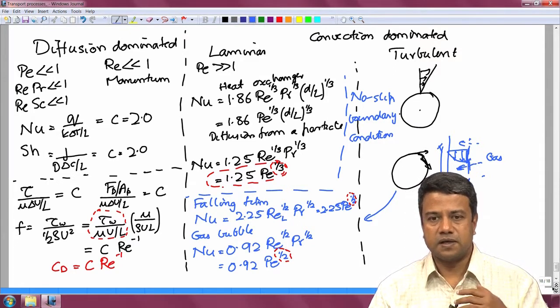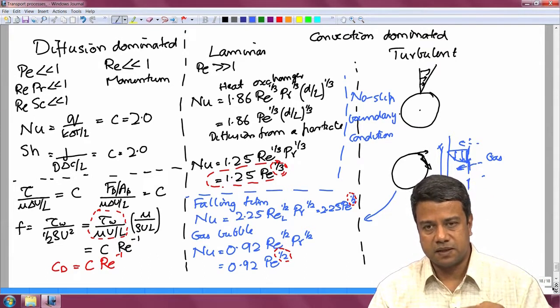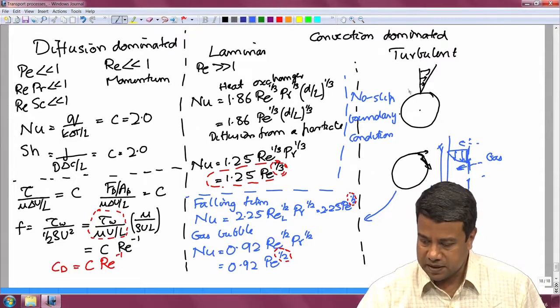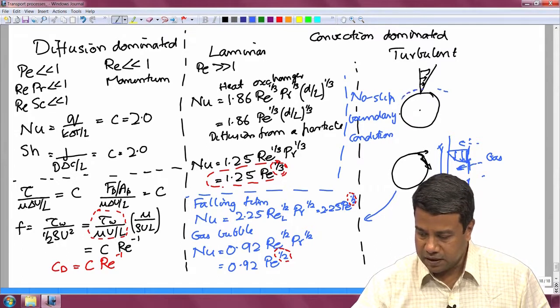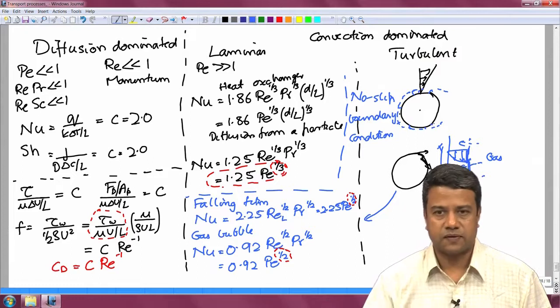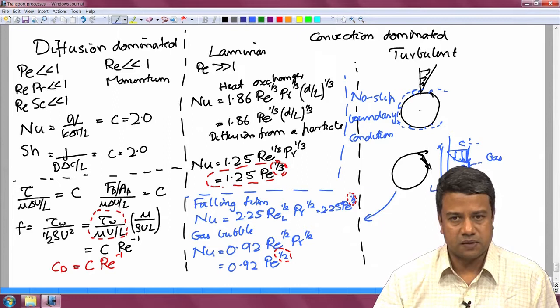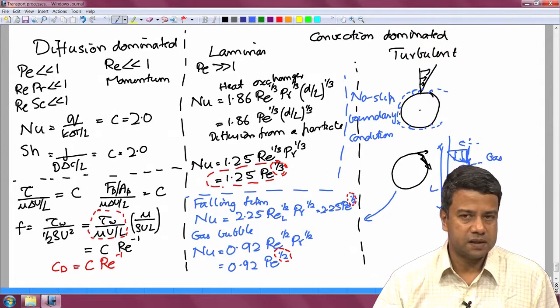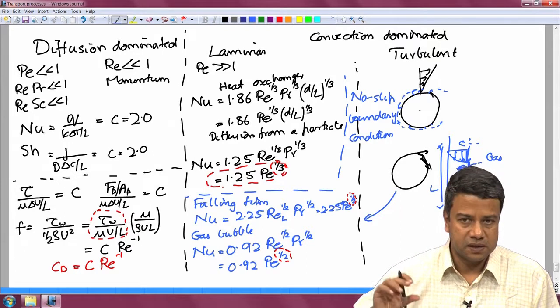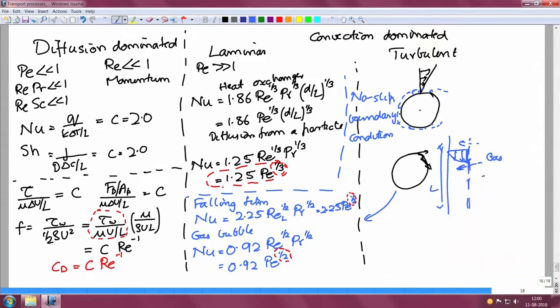When convection dominates, the speed at which it is being swept back will be much faster than the speed at which it is diffusing out, which means that the energy or the mass that is coming off the surface will be restricted to thin regions close to the surface. By thin, I mean that the characteristic distance is much smaller than the length scale in the problem, the particle diameter, the pipe diameter and so on.